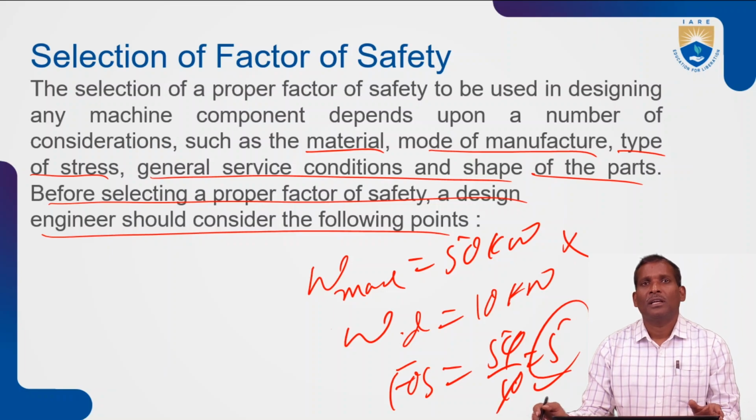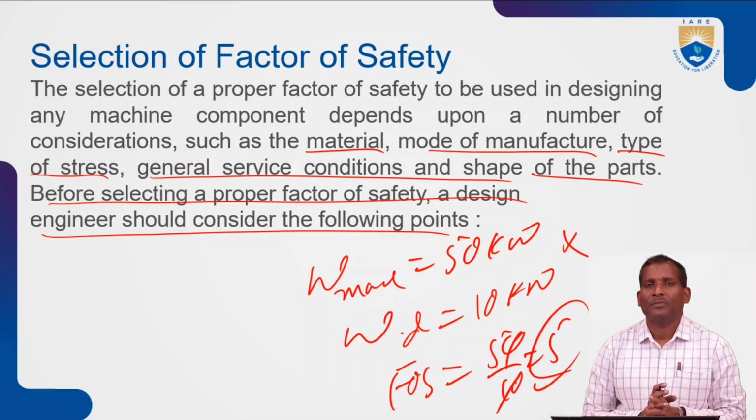That's why the factor of safety depends upon the material, and the mode of manufacturing process, which type of manufacturing process is required for a particular design. It may be machining or drilling or grinding. Then the type of stress, general service conditions and the shape of the parts.